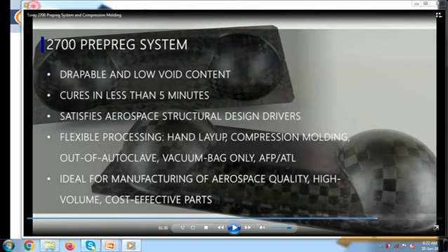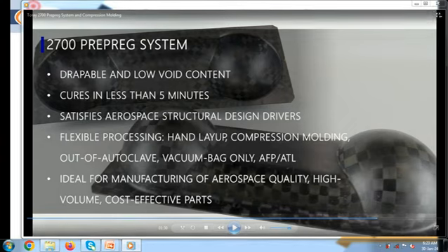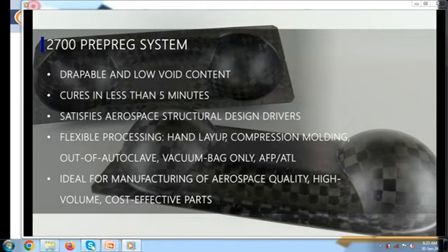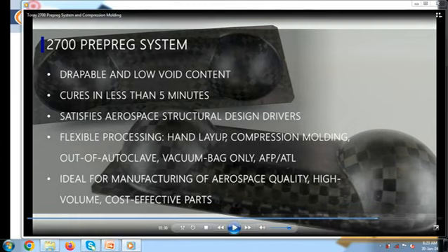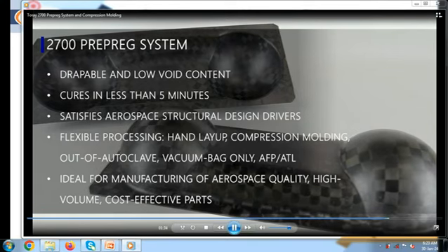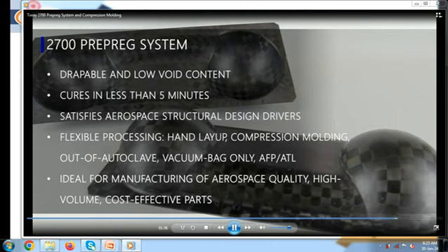Initially that sheet was very flat. Now after application of the load and after the curing period of 5 minutes we can view this kind of shape. These kinds of shapes might be required for many applications like vehicle bumpers and so on. Okay, so this is all about the compression molding process, how the compression molding process takes place.